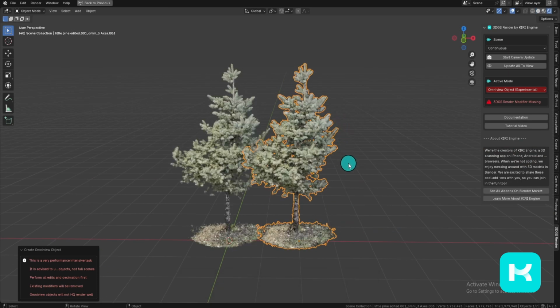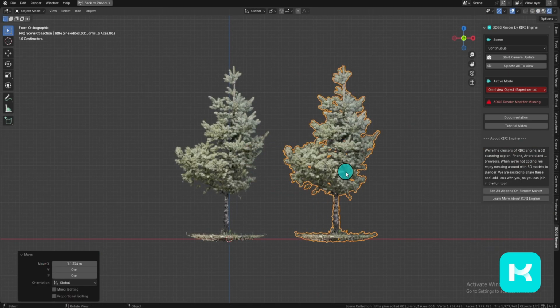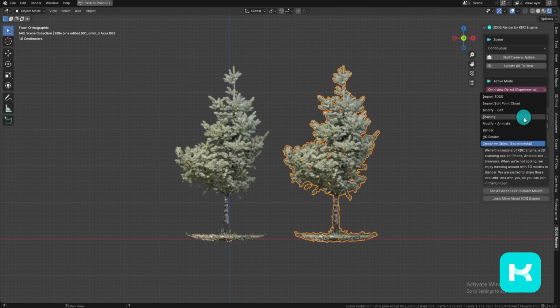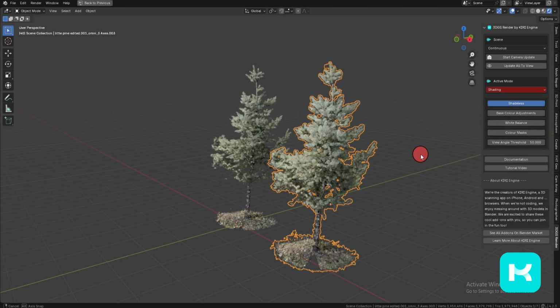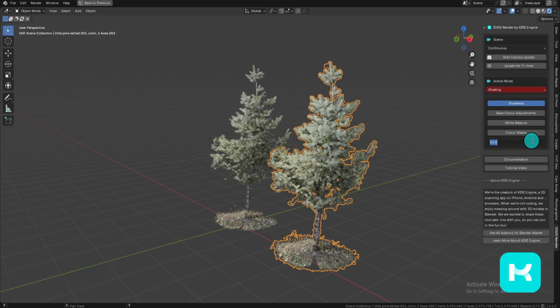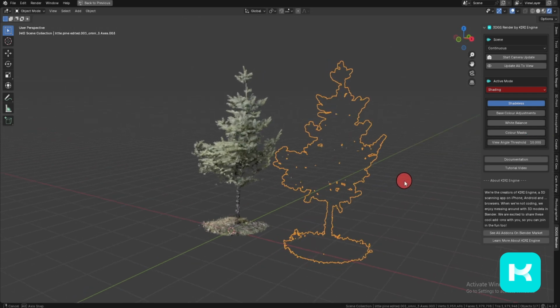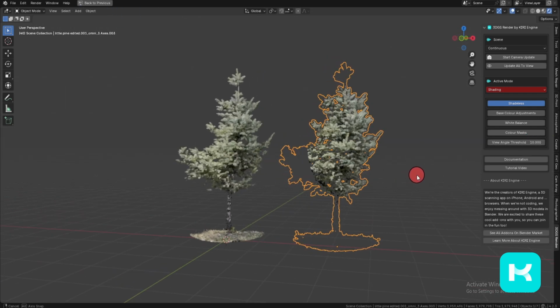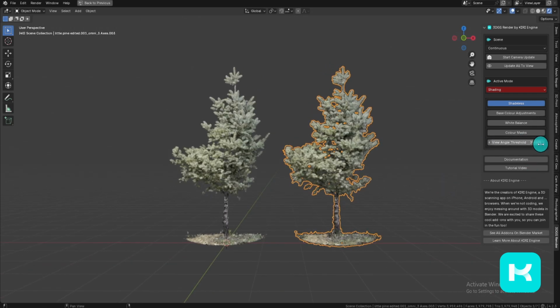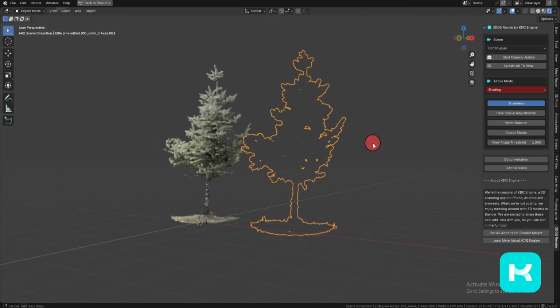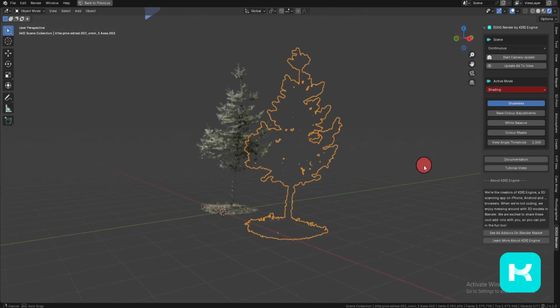If an Omniview object is selected, a new option will be shown in the shader menu, the View Angle Threshold. This is a value in degrees and will determine at how many degrees the current view can deviate from before a face disappears. If a value is set to 1, the face would only appear when looking directly at it.